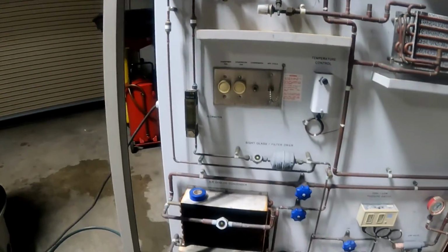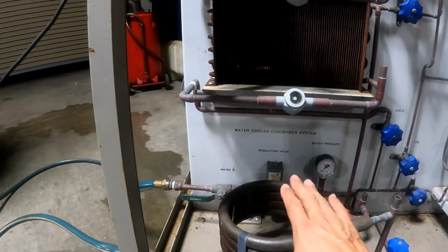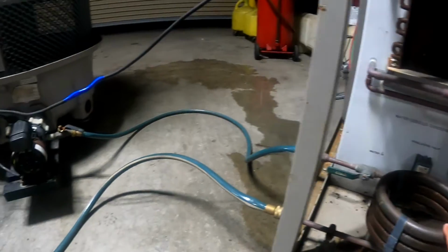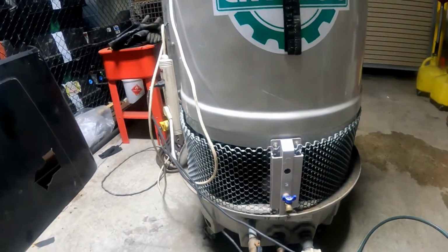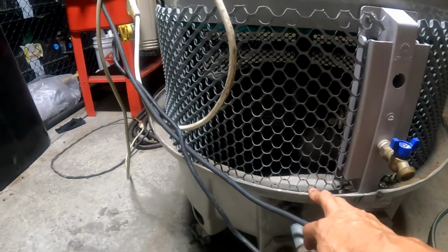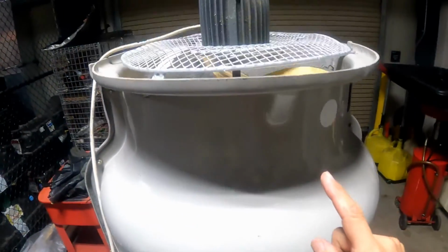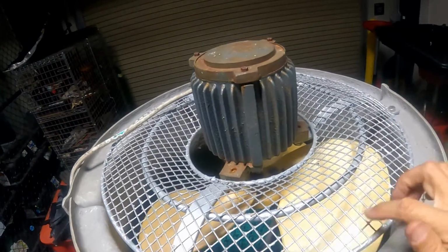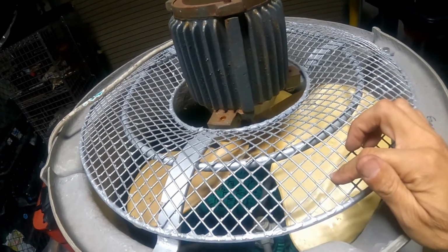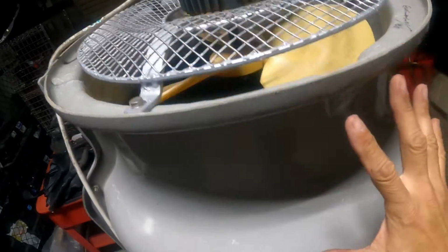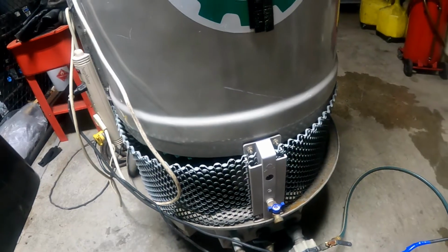Okay, we have two air cooled condensers and a raw water cooled condenser. The raw water is coming from the cooling tower. The cooling tower receives municipal water in the pool in the bottom, and the water is pumped up, and a fan on top. When the water reaches the top, the water drops by gravity, and the fan cools the water, and the water goes down by gravity, and the water is cooled.